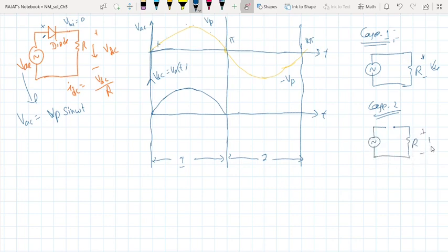Okay, so what voltage will the resistor experience, there is no voltage. Okay, so that means because there is no current flowing, obviously there is no path for the current to flow, then zero voltage will be experienced. Okay, so why zero voltage here, because 0 ampere current is flowing through it.